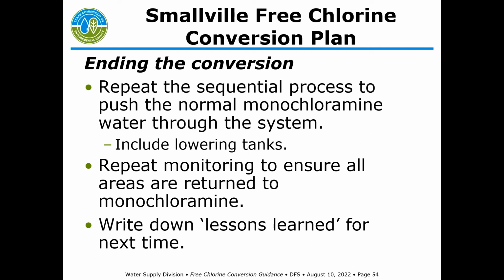So as far as ending the conversion, you're just going to do the same process that you did at the beginning, including lowering your tanks. That's very important as you flush monochloramine back. And then repeat the monitoring to ensure all areas are returned to monochloramine. And it's really important, this last point, write down lessons learned for your next time, because you're going to figure stuff out during this, like, oh, this would have worked a lot better for the next time, et cetera. So just make those notes and have those handy when you try to do your next free chlorine conversion.